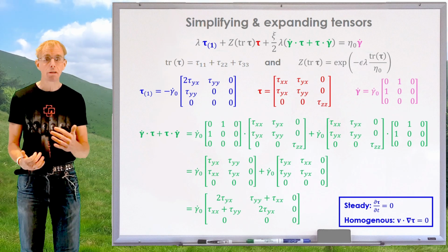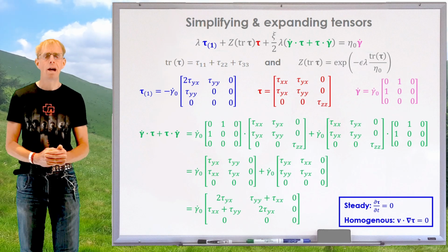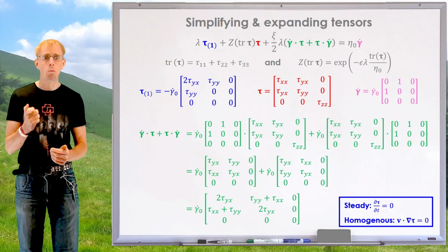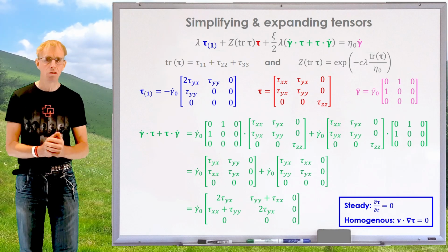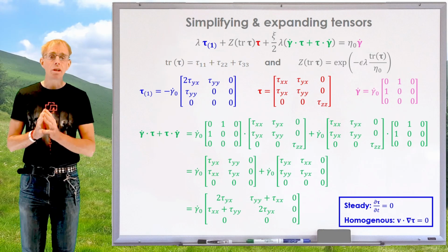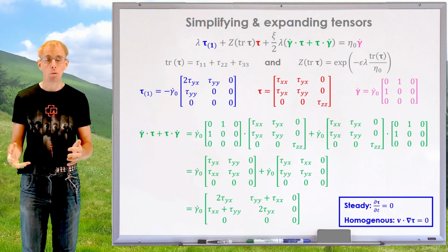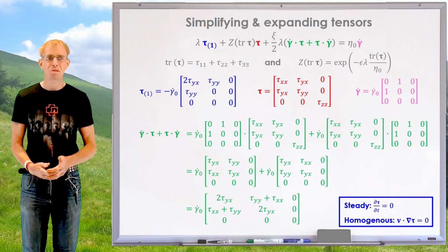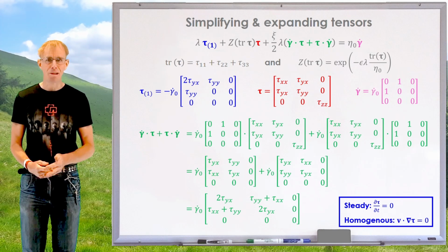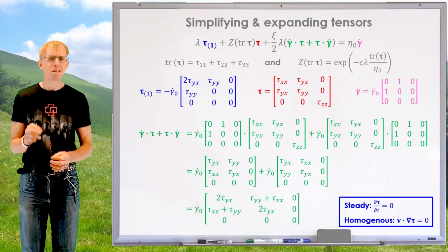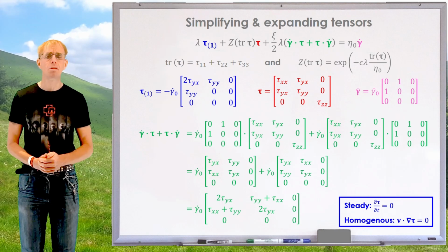So they're symmetric. And also we have the shear stresses, tau yx, featuring in the 1, 1 and 2, 2 positions, and that's symmetric. And so when you've done this operation, we are expecting a symmetric result because all the tensors in these equations are symmetric. And so if you obtain an asymmetric result, just go back and check your dot product because you've probably got something wrong.